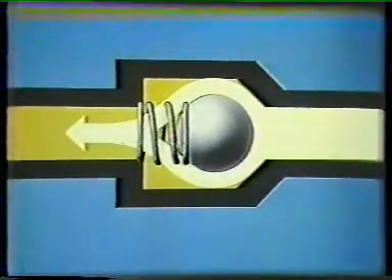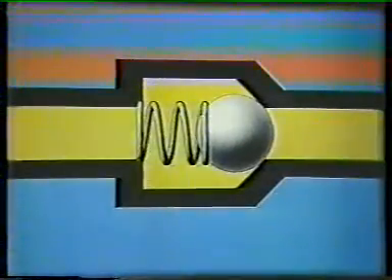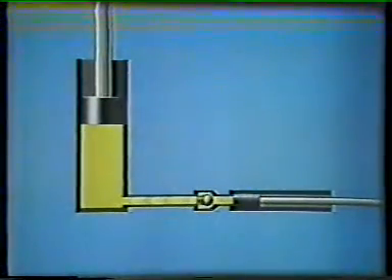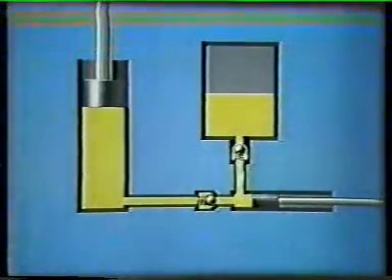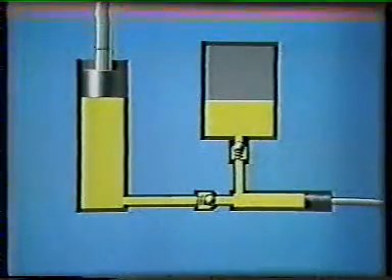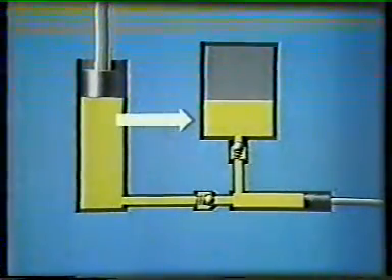Because displaced fluid is retained by the non-return valve, no further fluid is available for work in the smaller cylinder. This is overcome by the introduction of a reservoir and supply valve. We now have a system capable of raising a load, but to lower it again, we have to transport the fluid which is built up in the large cylinder back to the reservoir.